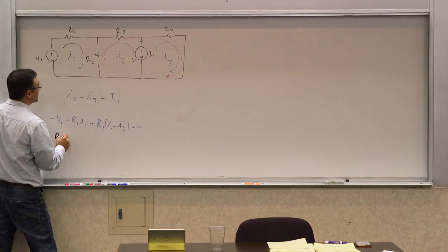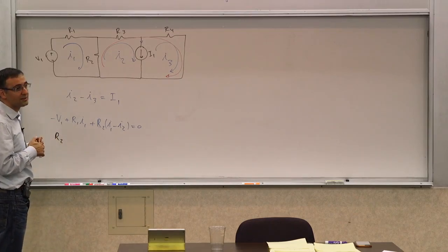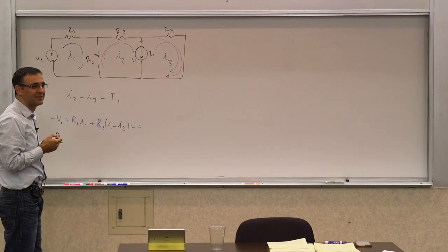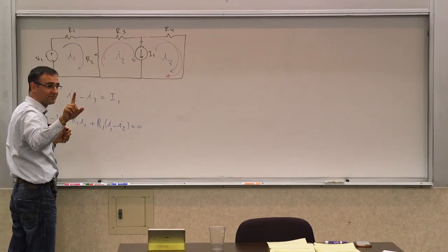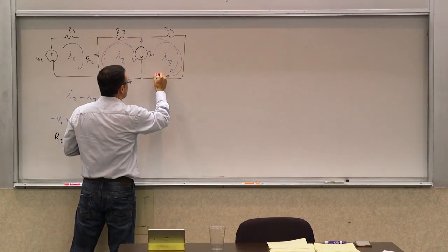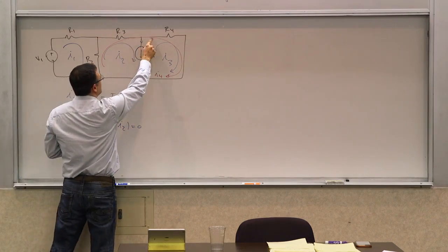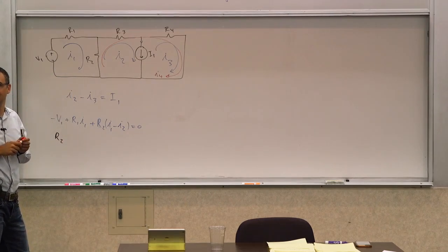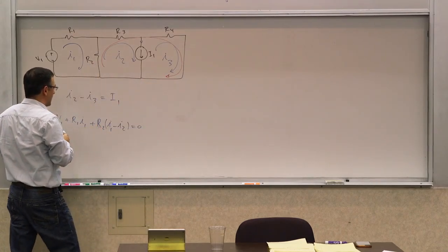R2 I, what are we calling the current? We don't need to call it anything. We already know what it is. The two currents are still there. Oh, okay. Right. So still use I2. You still use I2. Now, here's the reason. You can't define a new, I don't know, I4 here. Why can't you do that? Because that current is not equal here and there. You need to really write it still in terms of I1, I2, and I3. So you don't do that. Just write it in terms of those. Go ahead.